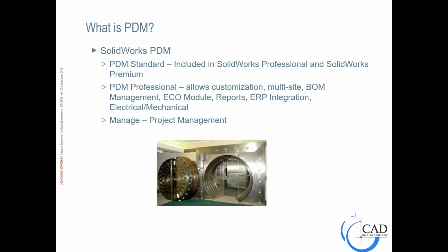There's also the higher end version, PDM Professional, which allows a richer experience. It allows customization. It has multi-site capabilities, allowing synchronization between different cities, different countries. It has BOM management. It has an engineering change module, a reporting module, allows for ERP integration, and also allows you to integrate electrical and mechanical design. And then now there's a third module to PDM, which is almost like Microsoft Project functionality inside of your PDM environment.